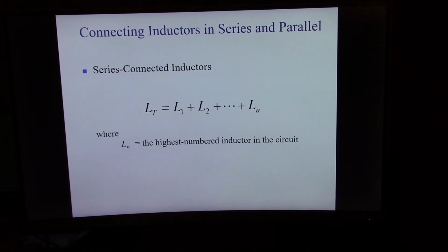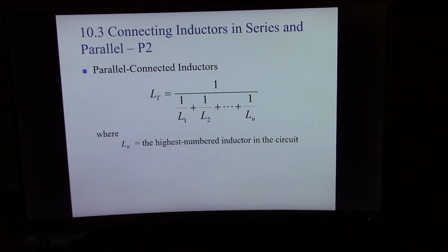When you have inductors in series and parallel circuits, it's very similar to resistors in series and parallel circuits. So if they're in series, then you just add them up. It's very similar to the resistance circuit. And a parallel will be the same thing. This is that reciprocal of the reciprocals formula. Or you can use the product over sum formula.